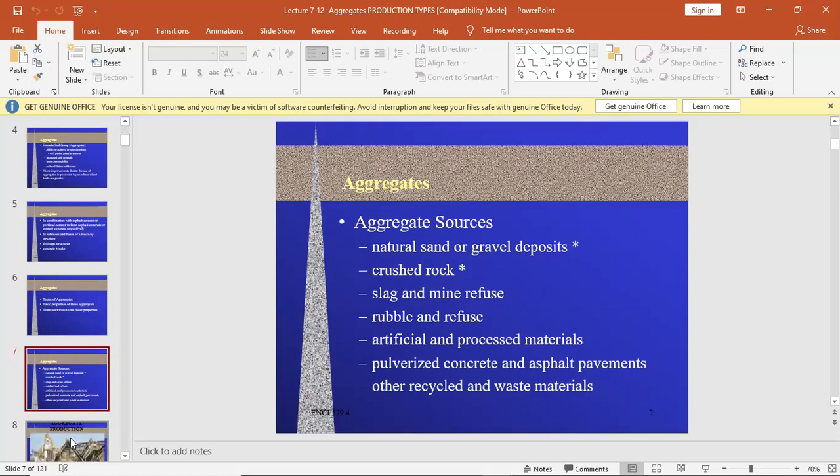It's very important to know the source. Whenever a highway construction contract is floated, the first thing a contractor asks himself, before giving a bid for getting the contract of this road, is whether he has a source of aggregate that is locally available or not. I am very firm on it, and I think it's a standard practice.